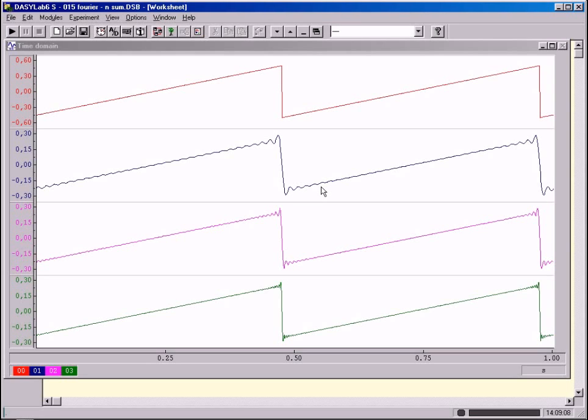As the sawtooth at the jump position can theoretically change infinitely rapidly, the deviation can only have disappeared when the cumulative function also contains an infinitely rapidly changing sinusoidal signal. That means frequency versus infinity. If that doesn't exist, a perfect sawtooth signal cannot exist either. In nature, every change takes time. The more sinusoidal signals contained in the spectrum are added, the smaller is the deviation between the cumulative curve and the sawtooth.